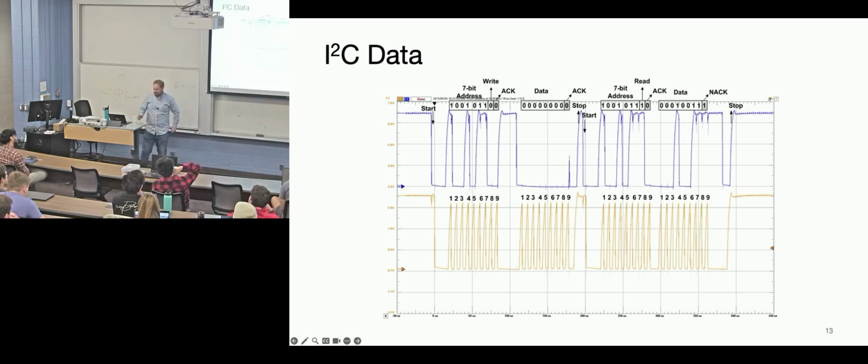Yeah. So the NACK is to check for a hardware bug, something like that? The ACK is for the peripheral, or the thing that you're talking to, to acknowledge that it's gotten the data. So here, let's say the controller was writing to address 100101110, and it was acknowledged by being pulled low. So that means that the peripheral acknowledges I've got that data. Do you see the reason why we have ACKs now?